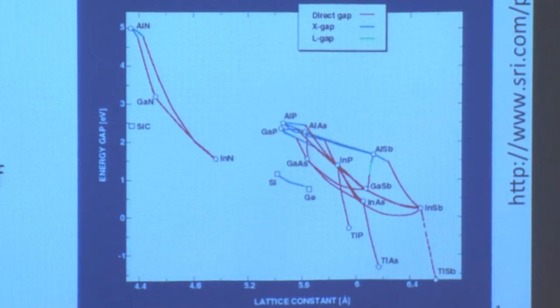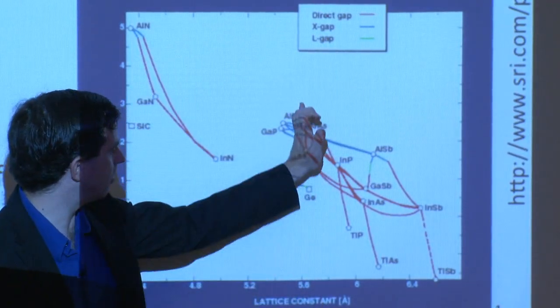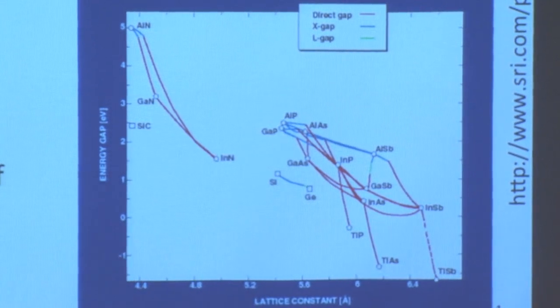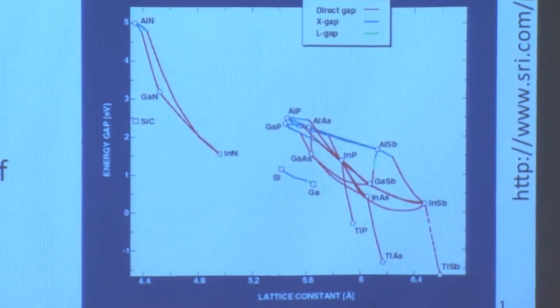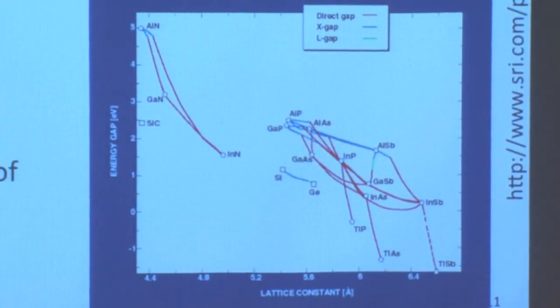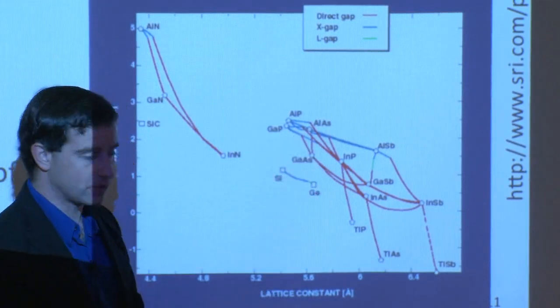And the energy gap here is important because you want maybe one material at 1 eV, one material about 1.9 eV, but you also want to make sure that they can grow on top of each other, that you're not going to get a mismatch at that interface, that the lattice constants aren't so different that you wind up with dangling bonds at the interface where you have an atom coming down and nothing on the other side for it to bond to. And so you need to make sure that the materials that you grow are matched in lattice constant, but varying in band gap if you're trying to grow a multi-junction device, a very high efficiency solar cell device. And so the growth or matching of materials one on top of another is important, especially for the multi-junctions, also for some of the single junction materials if you really want to minimize the interface recombination.